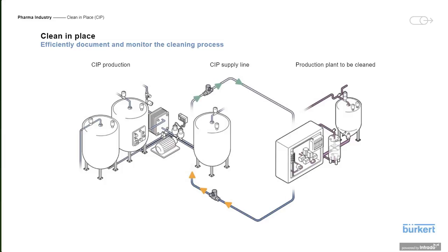Basically, absence of detergent or acid or other residue that may be in that rinse stream to drain. Basically, by using the dimensionless density factor, as Hendrik pointed out earlier, you're able to use that parameter, and in some cases, depending upon the accuracy required, you could possibly even use FlowWave's readout and convert to an actual conductivity value without the need for an additional conductivity sensor.